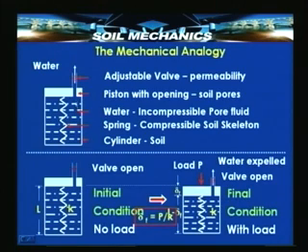through which water can go out, this arrow, but there is also an adjustable valve here, which is capable of controlling the flow of water out of this cylinder when a load is applied, and this in fact is very crucial, and it is this which represents the permeability or the coefficient of permeability of the soil, and this is what is responsible for inducing into this time dependency.